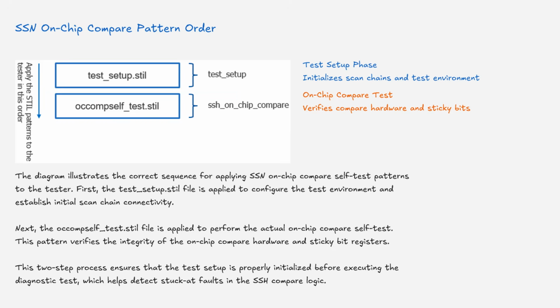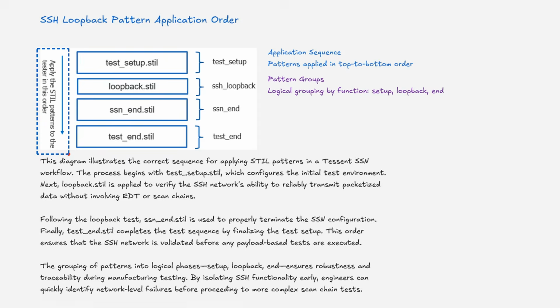This two-step process ensures that the test setup is properly initialized before executing the diagnostic test, which helps detect stuck-at faults in the SSH compare logic. This diagram illustrates the correct sequence for applying STIL patterns in a Tessent SSN workflow.